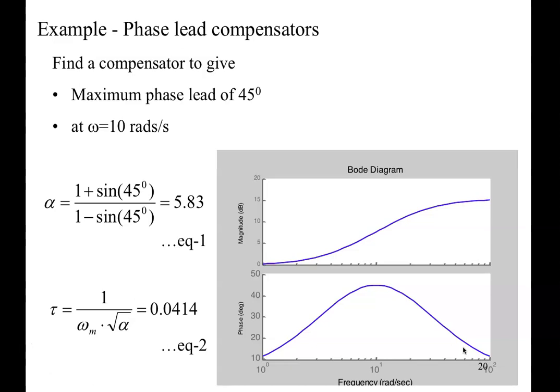Now of course, if you notice, the magnitude also changes with frequency. So it's not a constant, it changes with frequency. Because when you consider K times G, you add magnitude to magnitude. So you add the magnitude of this Ks to the magnitude of Gs. This will change the overall magnitude. Therefore, your crossover frequency will change.